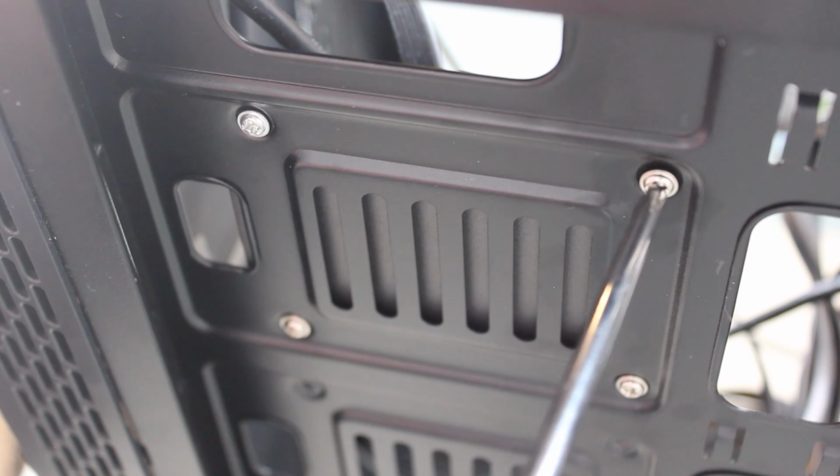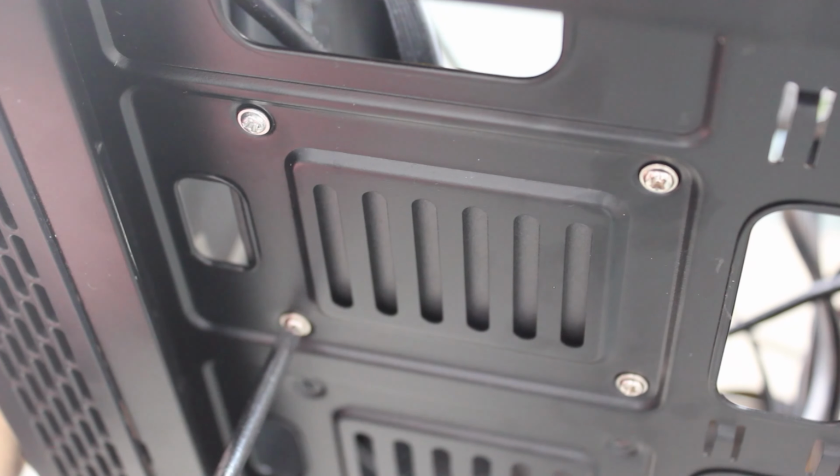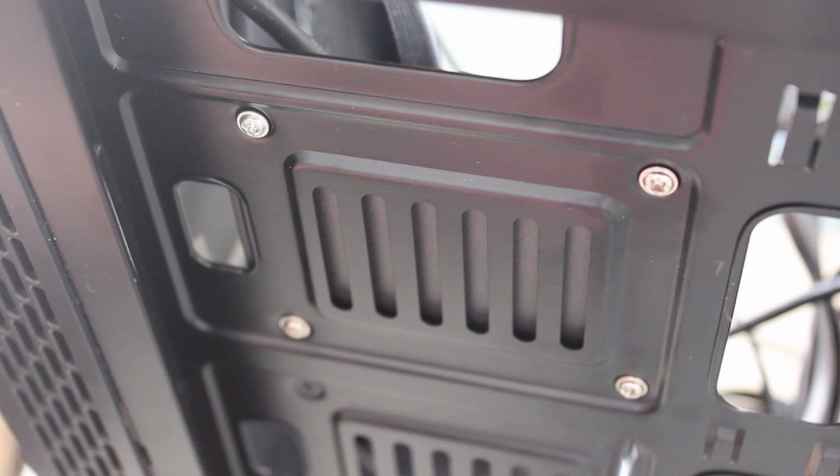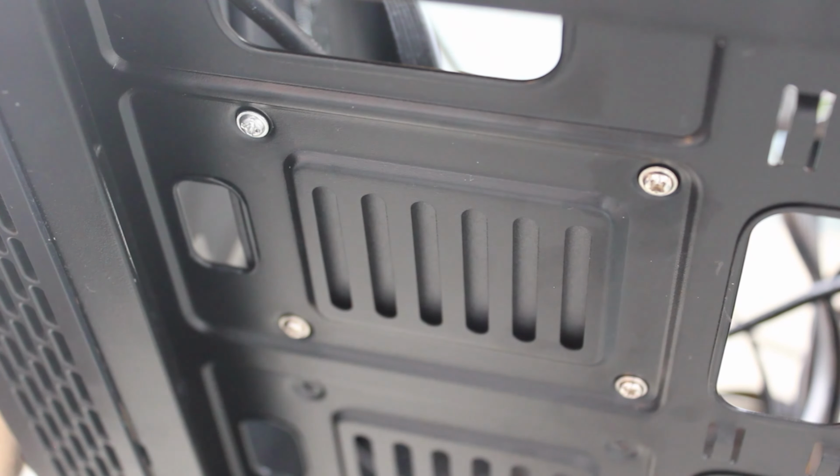The first screw that I put in is generally very loose, so I can move the storage device around to make sure it is aligned with the other screw holes. You don't want to over-tighten because this can damage the thread of the screw holes. Essentially, just make sure they are finger tight.